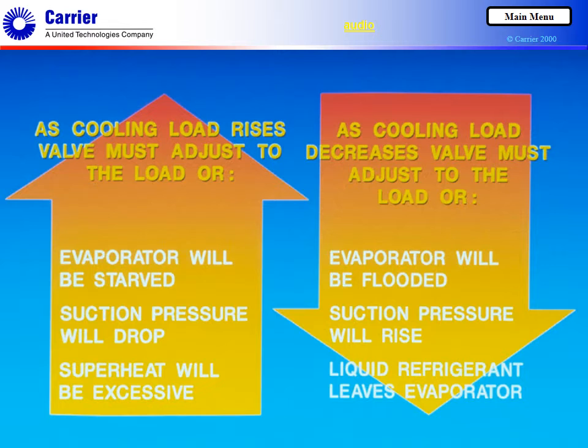If it is not, the evaporator will be starved, the suction pressure will drop, and superheat will be excessive. The result is that system efficiency and capacity will suffer. As the cooling load decreases, the valve must be closed a little. If it is not, the evaporator will be flooded with excess liquid refrigerant, causing the suction pressure to rise and liquid refrigerant to exit the evaporator. System performance will be poor, and the compressor may be damaged.